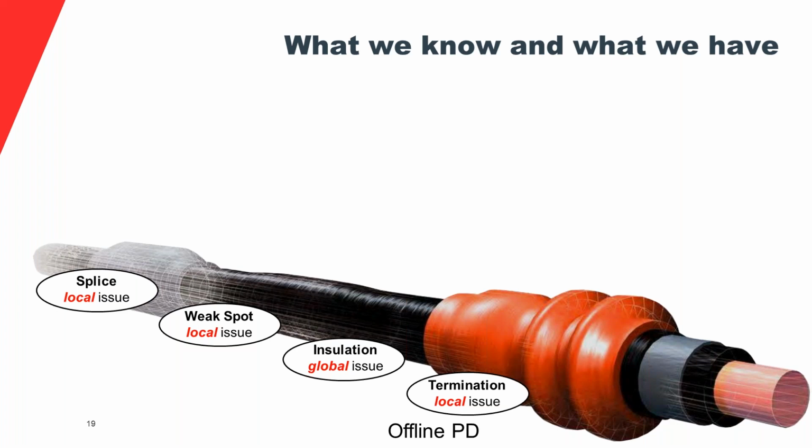It's an unaltered part. It comes out of the cable manufacturer's plant, tested in a Faraday cage, up to 4 times operating voltage. For the extruded cables, anything that is near 5 picocoulomb in terms of magnitude gets disqualified as a batch. So you should get these days a pristine cable out of the factory. But then installation happens, you have to splice multiple drums together. If it's a longer cable, you have to put terminations on, you have to put splices in,